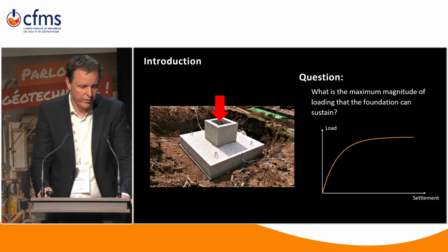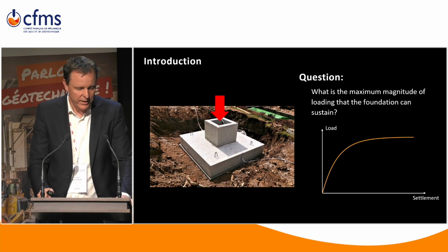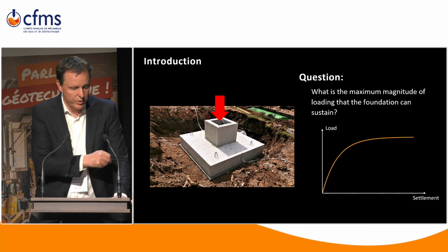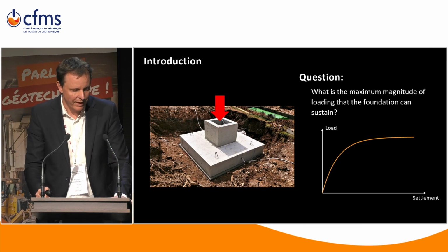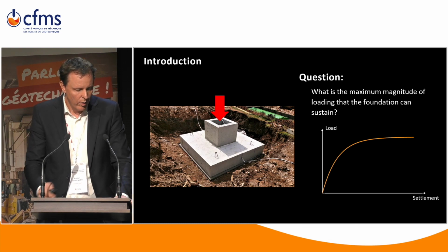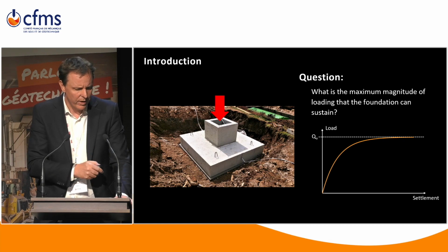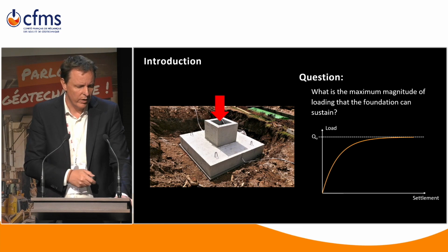In asking that question, we implicitly understand that if we were to increase the load on top of the foundation, then we would have some settlements, and we would have a load settlement curve that looks more or less like this, at least ideally or schematically speaking. What we are interested in is not really the full load displacement curve. We are interested in what we call the ultimate limit load, the maximum load that the foundation can sustain.